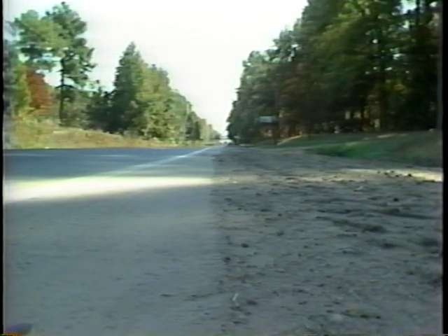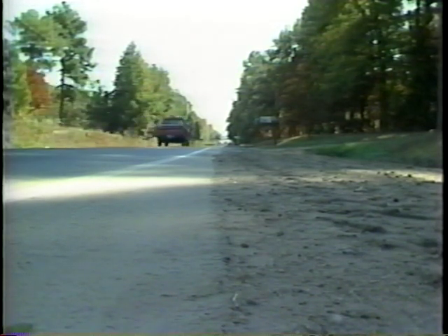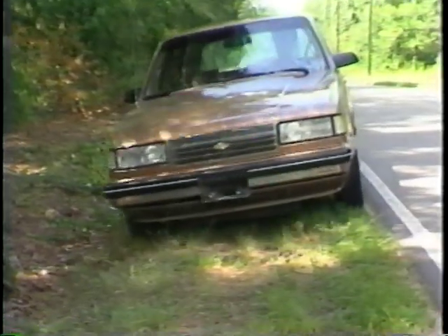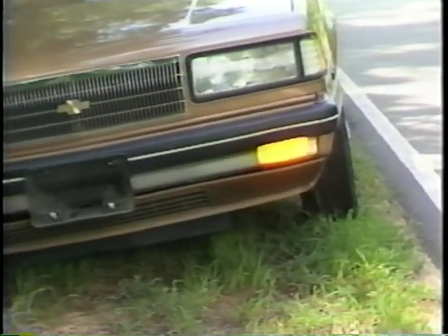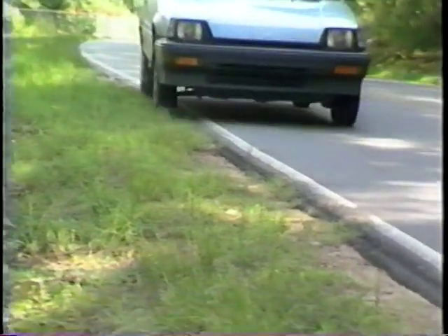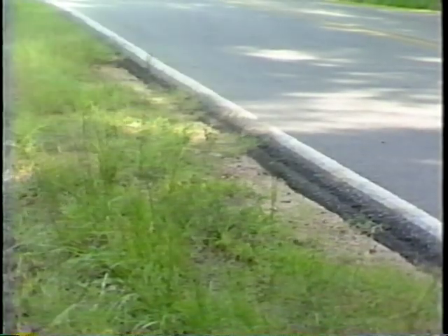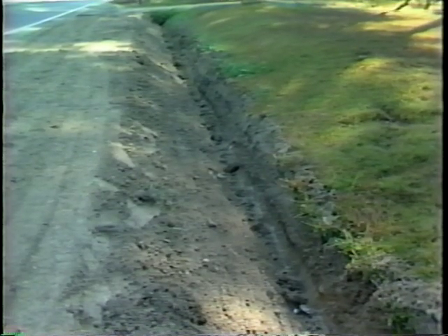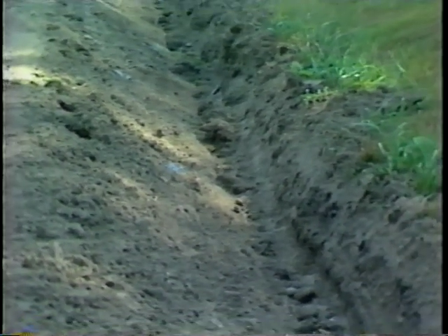The shoulder protects and gives lateral support to the pavement edge, base, and subgrade on each side of the road. The shoulder provides an emergency stopping area for the traveling motorist. It also provides a recovery area for vehicles that may leave the road surface accidentally. And probably the most important function of the shoulder is to provide a surface to drain water from the pavement surface into the roadside ditches.